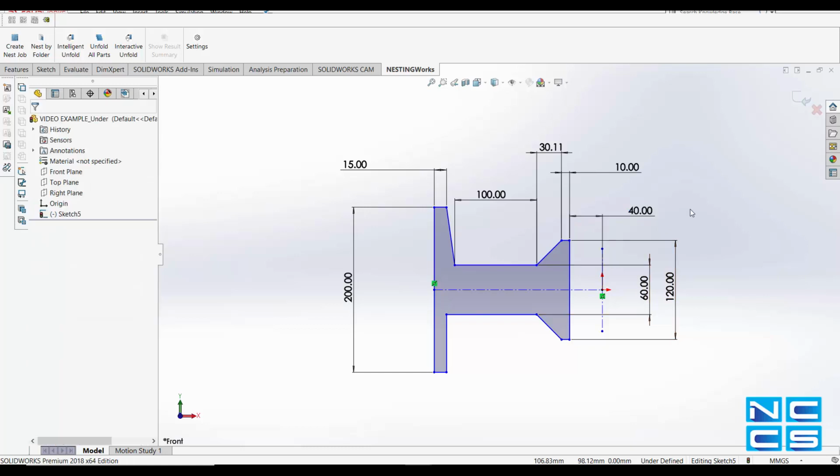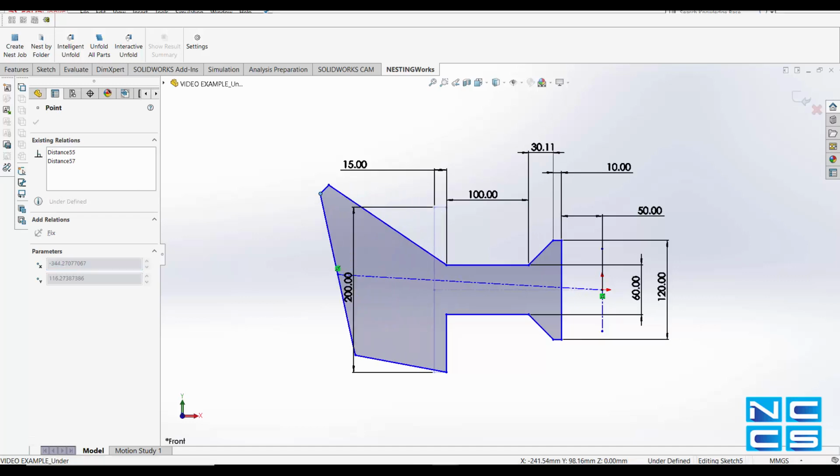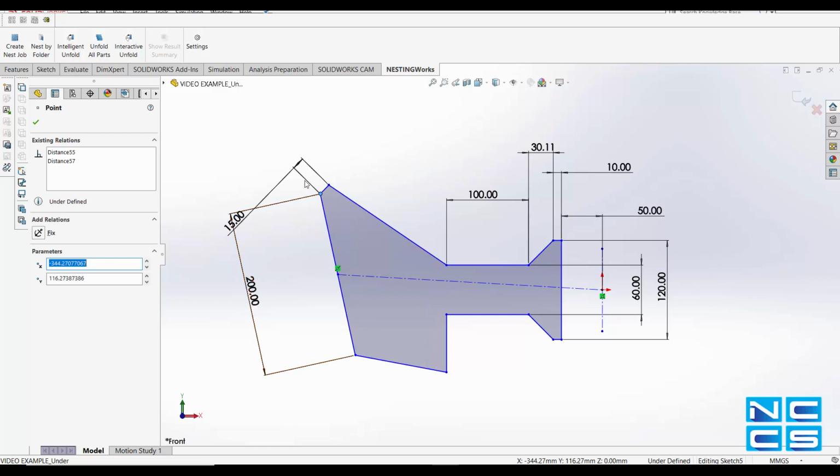See here how Solidworks hasn't really moved the shape forward, but has stretched it and thus changed the main body of the sketch. The way in which Solidworks thinks is very black and white. Every defined feature is law and will not be changed. However, anything that isn't defined in the eyes of Solidworks is not of importance and therefore can be changed.